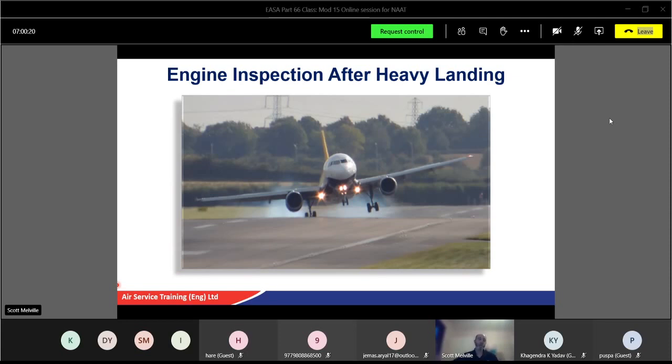Do a physical, put your hand on the LP turbine and spin, well, or the LP compressor, sorry. Spin the compressor. Does it sound right? Does it feel right? And then even actually hand turn the gearbox to check the HP turbine. And if you've got a triple spool, get a tool to check the IP turbine as well, an IP spool. Make sure everything is free to rotate, because if the bearing's been damaged, it's going to feel notchy and gritty, not very well at all.